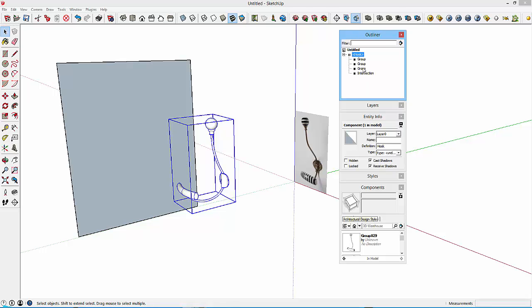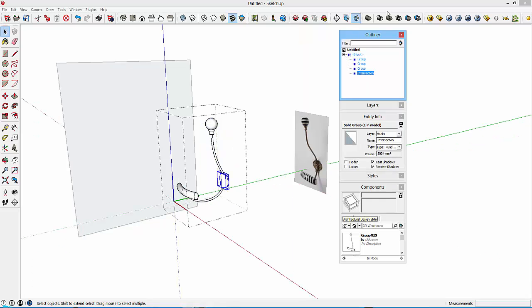I've then got the intersection. That's this bit. This is a Boolean intersection from the solid editing tool, part of the SketchUp Pro tool set. This bit is the sort of thing you put, I don't know, a hat or something on, I guess. And then you've got this ball and brass ferrule at the top. And this thing here is the sweep, which is the hooky bit.